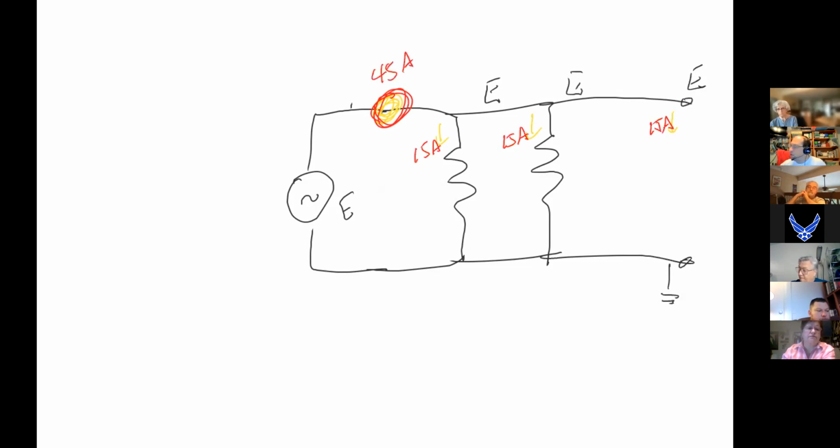That's right. So this might be a number 14. This might be a number 12 wire. This one might be a number 12. Those are known as AWG, which is a wire gauge. This right here is probably like a number 6. So it's a much heavier wire. And that is your main bus wire that feeds everything in your breaker panel.